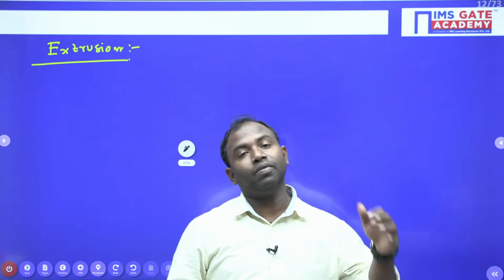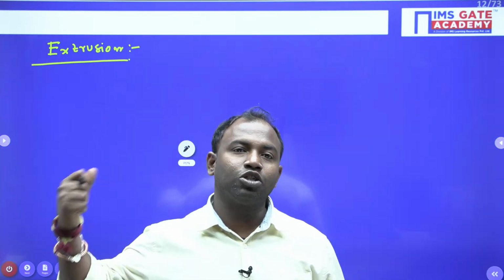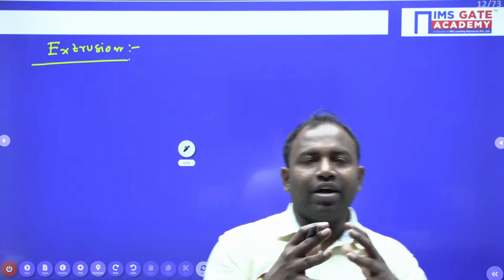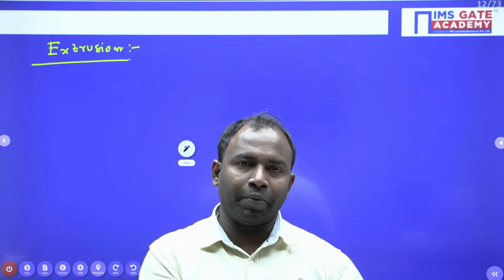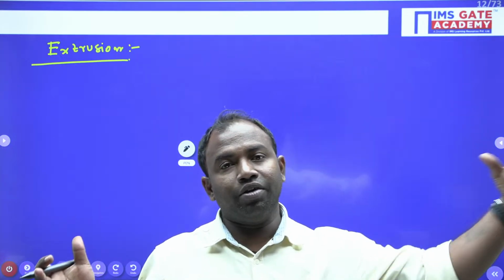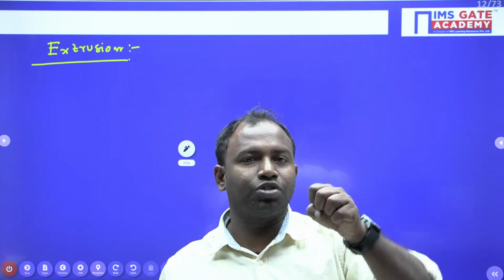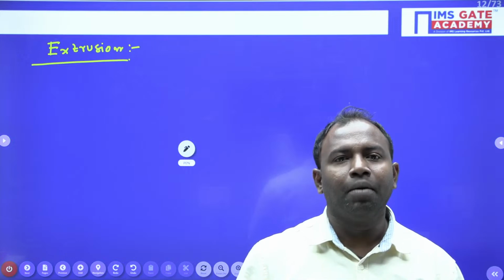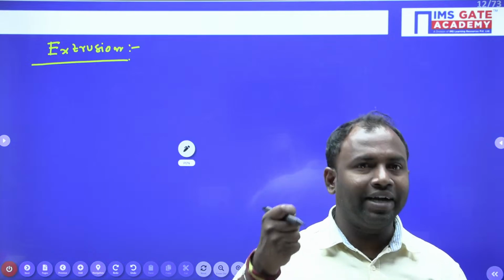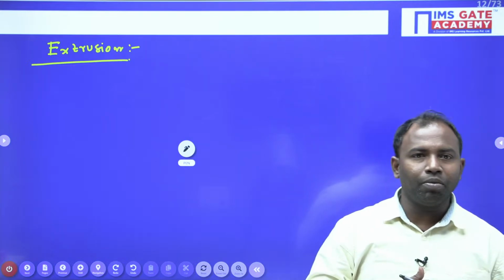Whatever limitation we have seen in drawing, that is a limited reduction, and the load has to be applied for a long time for converting the elastic deformation into plastic deformation. In the extrusion process, if you apply the forces from the backside of the material, the stress induced is the flow stress, so any amount of deformation is possible. So the highest amount of reduction takes place, and there is no need to maintain the load for a long time for converting elastic deformation into plastic deformation. Clear, everybody? Hope you understand.